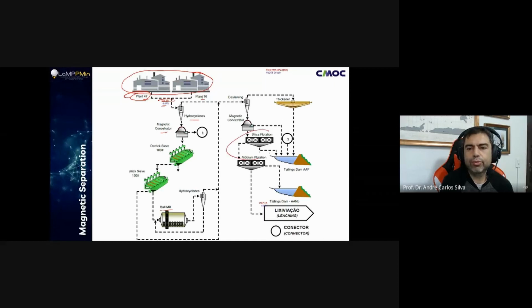and it goes to the flotation stage, silica flotation followed by niobium flotation, and in the end we have something like 0.67 tons per hour. So let's consider again here 150, and I'm going to produce 0.67 tons per hour.